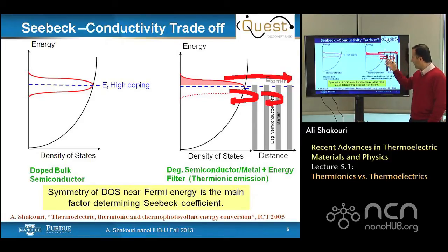And again, when we are talking about this case, it is an effective thermoelectric material. Each of these barriers is on the order of an electron mean free path. That's what makes sense. That's what is needed to get this filtering. But we don't want to run it in a high voltage or high current case. It's not a nonlinear case. We can still define an effective Seebeck coefficient.